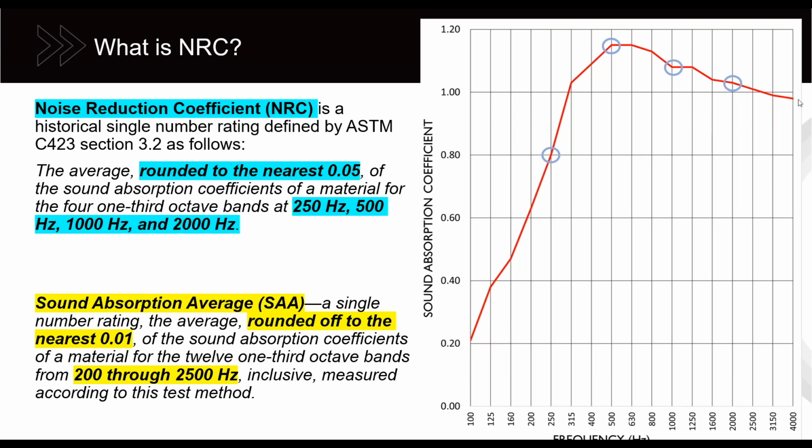It's a pretty good representation of, let's say, a 2-inch thick sound absorption core, just generally. You see the performance is very different at different frequencies. Above 300 hertz, you're above 1.0 for most of the range, but then the performance drops at lower frequencies. So it's harder to absorb lower frequencies generally.